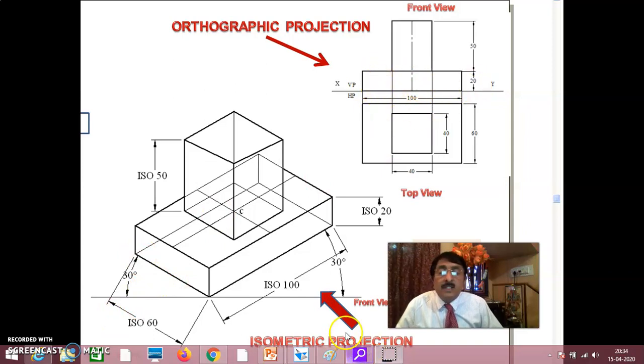Okay, let us now say it is this way. 100 by 20 square you draw. Immediately draw the projectors down. This is anyway 100, and this length will be 60. This is 100 by 60. If you look at the top view and looking at the height of 20, you immediately know it is a rectangular prism, 100 by 60. Height is 20. Okay.